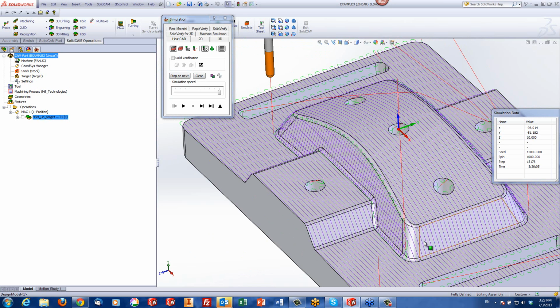Now, there's one other option I can use because some people will say, I prefer working on these surfaces going back and forth, but a little more, with a little finer steps. So, what did we do before? Before we did constant Z. Constant Z, as we said, works very nicely on steep areas, whereas linear works nicer on shallow areas.